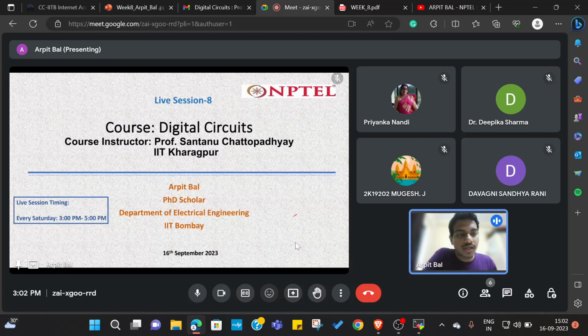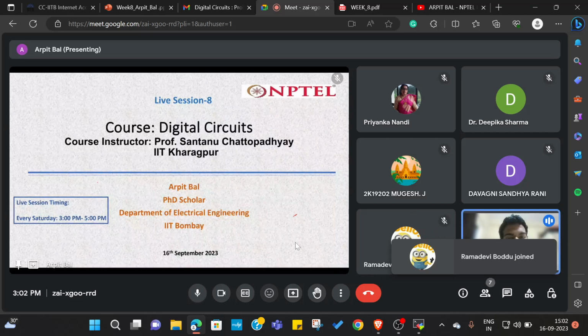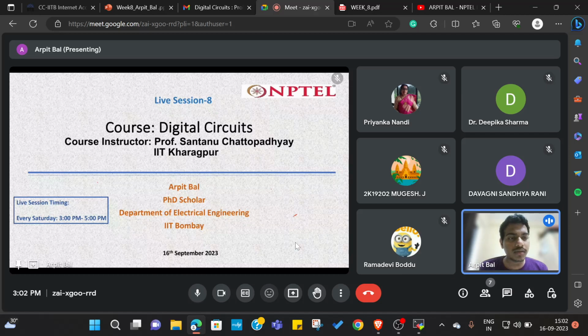So basically what we were studying till now is related to digital electronics, but the real world is analog, right? So whatever computation or processing that we are performing in the digital world, it has to somehow interface with the real world, right? And the real world is analog. We can't listen to something called digital music, so it won't make any sense to us. So we will need something to convert the digitally processed data into something analog, right? And similarly, we need something to convert the analog data.